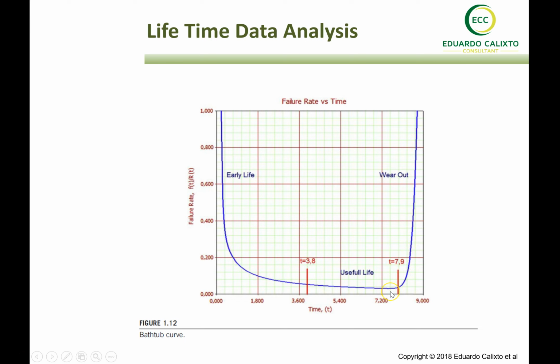So for mechanical parts that have wear out degradation, we need to define this point when the failure rate starts to increase. If you are able to define clearly this point, we will be able to define when to carry out some non-destructive tests or even schedule maintenance or inspection to assess the equipment health condition in order to avoid such failures happening.